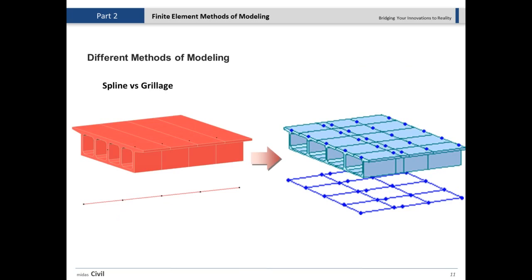To understand this method better, I can just show you this diagram. In these diagrams, you can see on the left side, the entire box is modeled with only one beam. But as I said, we can't really model the behavior of the structure because it's pretty wide and it doesn't work as a single rigid part of the single box.